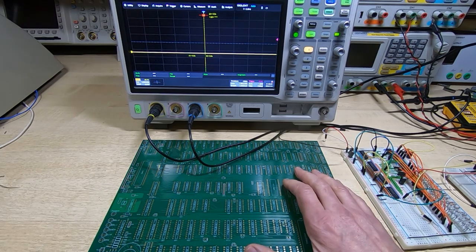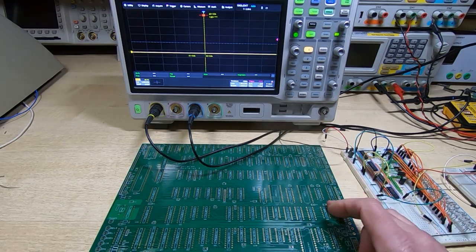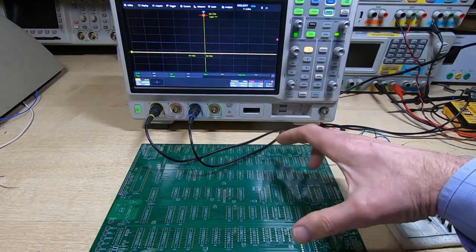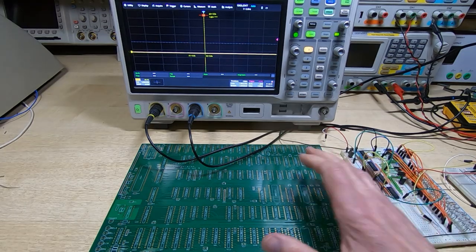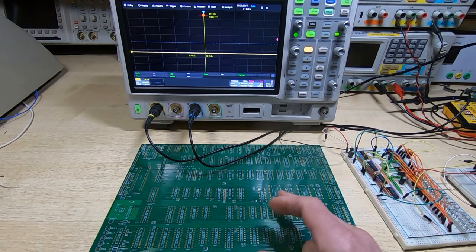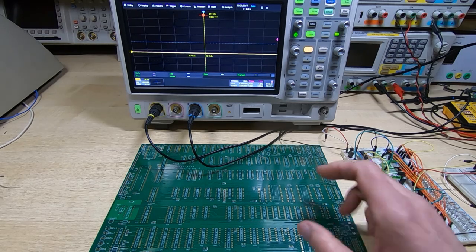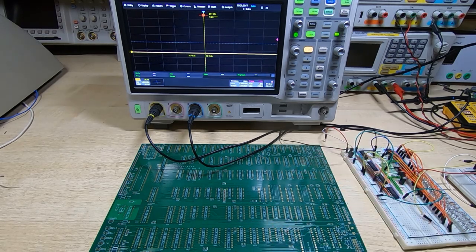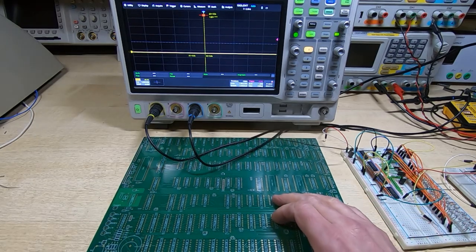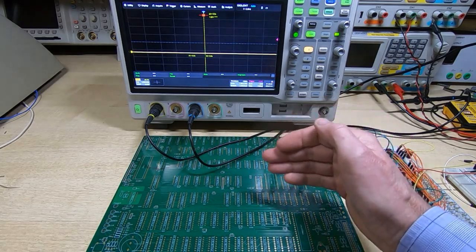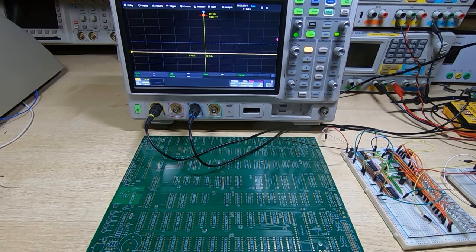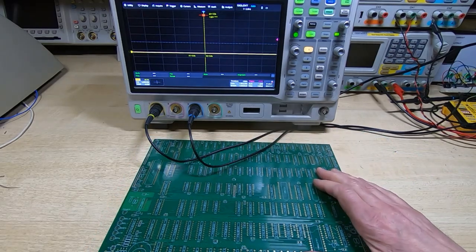Now the version 5 board, which is this one, is also a 4-layer board, and I've gone down that route because I have the option of either making the board even bigger to allow decent power traces. The power requirements on this board are obviously a lot higher than the version 4. Or if I went for a 4-layer board, I could keep the board relatively compact and use a ground plane and power plane, which is what the two internal layers are. So there are no traces as such on the internal layers. We've still got the X and Y traces on the top and bottom layer, but the internal layers are ground and power planes.